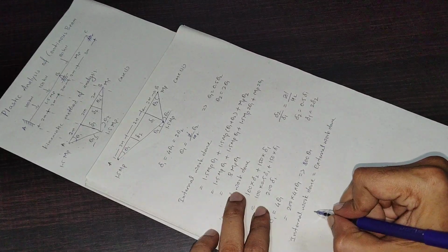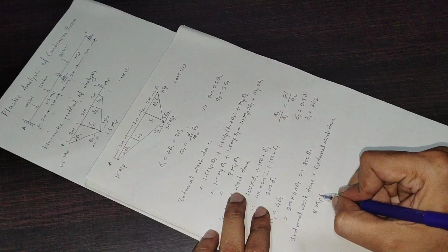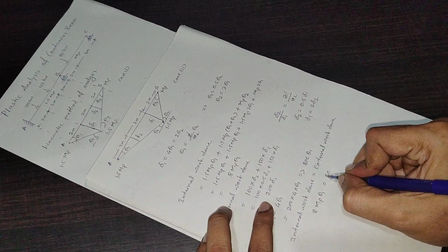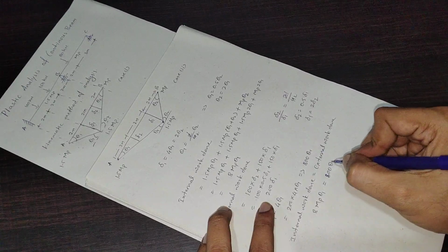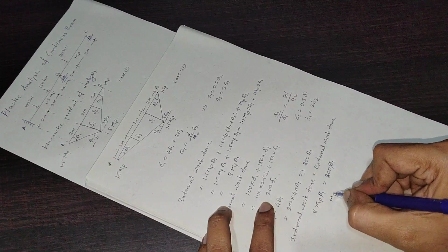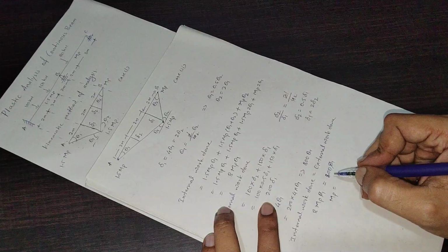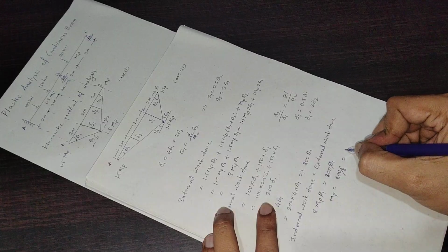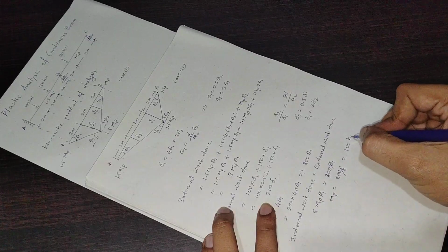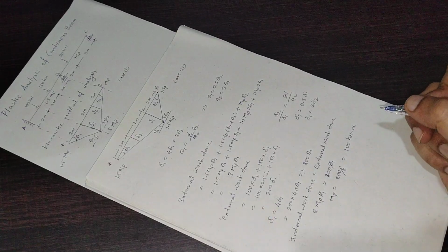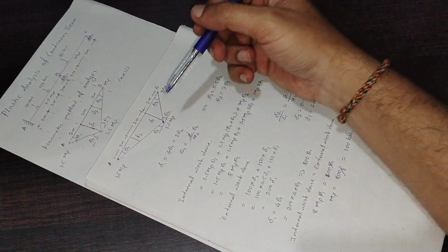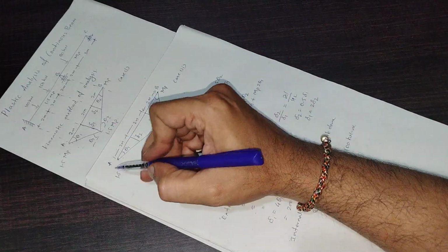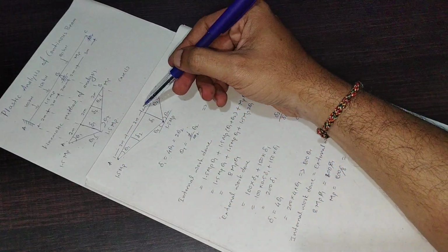So if I equate this, internal work done is 8 Mp theta 1, external work done is 800 theta 1. So this will get cancelled. Thus Mp is 800 by 8, which is 100 kilonewton meter. So this is for case 2 or second mechanism for the span AB under the load of 150 kilonewton.